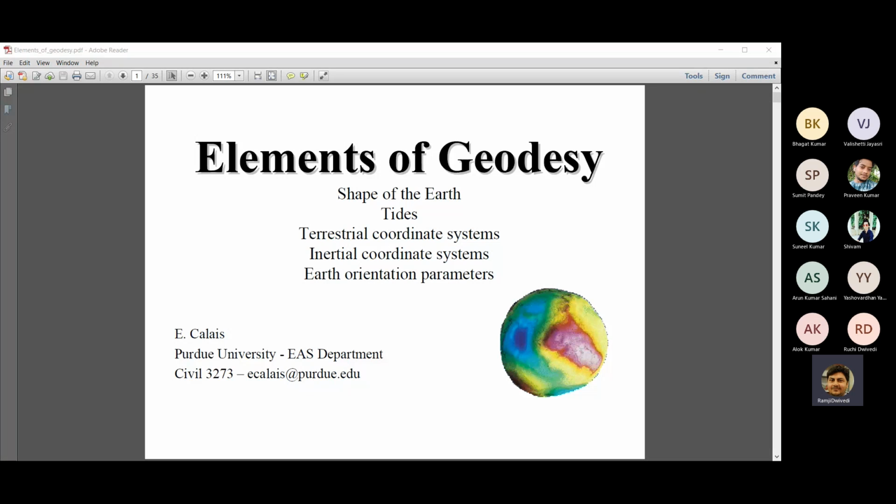and the so-called heights which GPS is measuring are called ellipsoidal height. We discussed at a certain point in the last semester that the heights we get from GPS are ellipsoidal heights, and the heights we get from the local mean sea level survey are known as orthometric height. So the two heights are different, and they differ by one term which we call geoidal undulation, or capital N value, for which we have seen the whole globe map, because various satellite missions are in space for studying the gravity of the Earth.